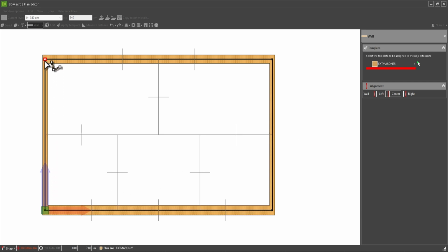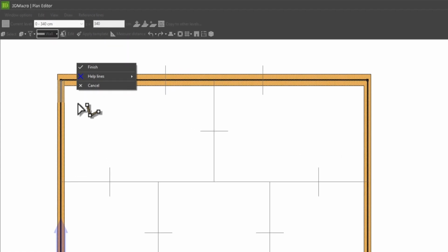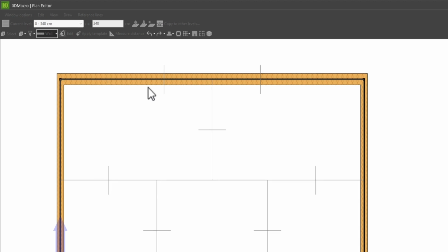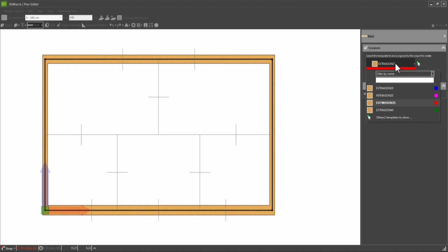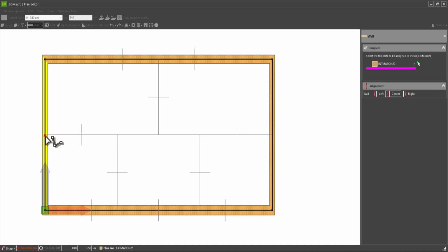After drawing the plan line, right-click and from the context menu select End or Cancel, to cancel the last point, or Escape from the keyboard to exit the command. We continue drawing the interior walls of the building. We select the format, that is the type of element in the right panel, and in the graphical environment we draw the plan line starting from the intersection with the already drawn plan line.